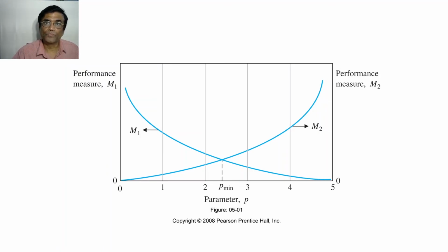And actually, there is a trade-off between these two. If you have a system which is extremely maneuverable, then its stability will be in question. And if you want a system with greater stability, a robust system, right, then maneuvering it will be problematic. So this is a rough example I gave you, so that you will understand that in control system design, there could be conflicting performance measuring criteria.